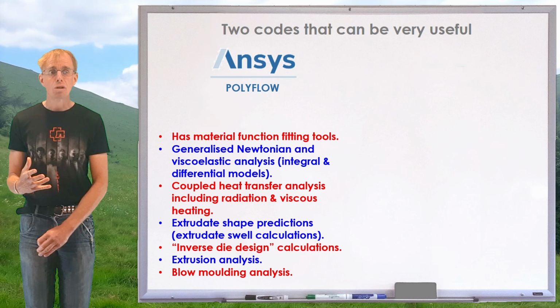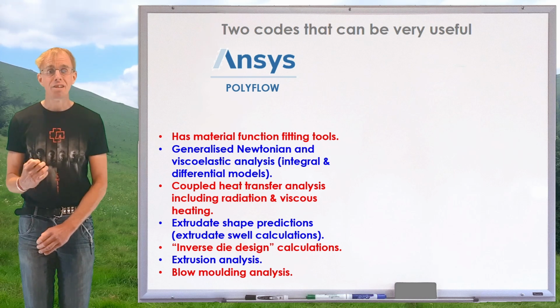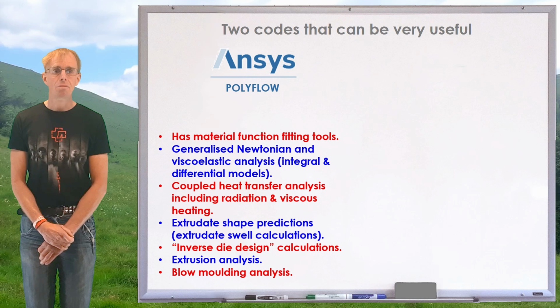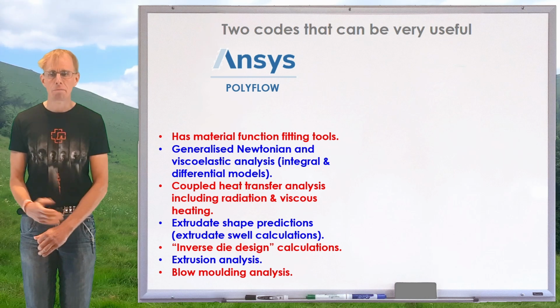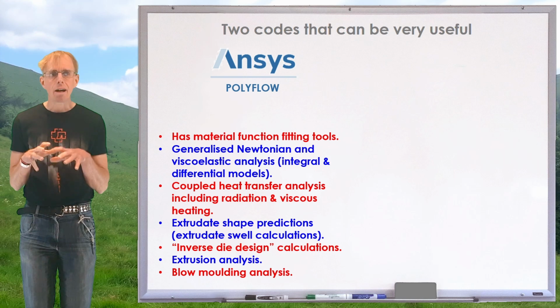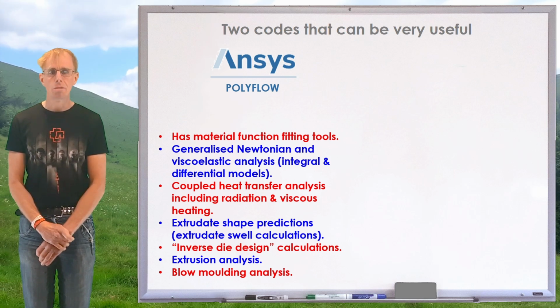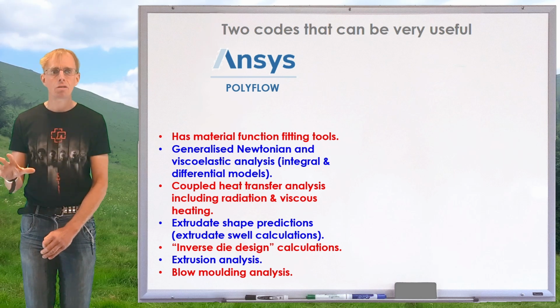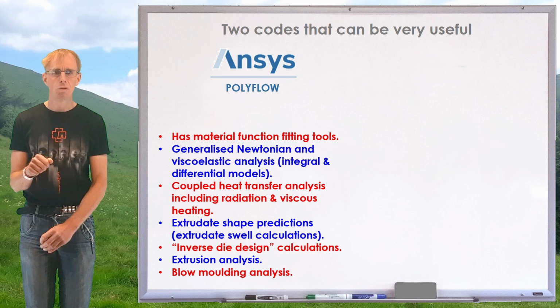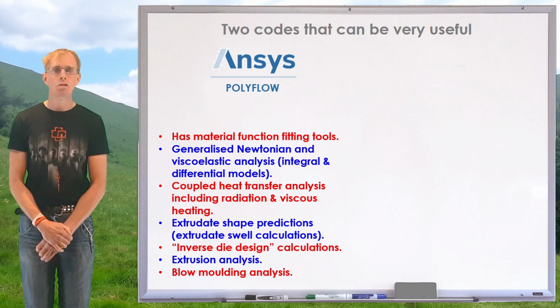So being a commercial code, this isn't cheap. Being viscoelastic, you will be wanting to run this highly parallel. I used to run Polyflow on 12 to 15 cores, and that gave a little bit of insight, a little bit of an inroad into some of the problems that I was trying to solve at the time. And that was typically limited to simple differential viscoelastic constitutive equations or thermally coupled generalized Newtonian fluids.